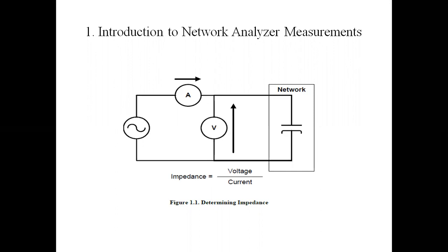Actually, before the network analyzer, determining the reflection coefficient of a circuit required you to manually calculate the phase of the reflection coefficient, one frequency at a time, on a piece of paper. This manual process required you to first find the maxima and minima of the standing voltage wave in a slotted line and repeat this process for all the frequencies. So it is safe to say that if the vector network analyzer had not been created, the high frequency community would look very difficult today.